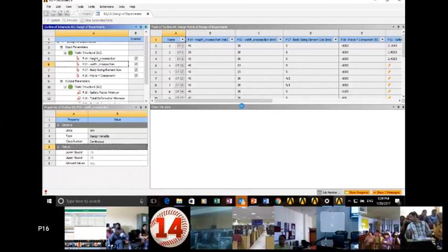Once you are done with the actual optimization of the structure, you will go for Six Sigma analysis. That will be the final step, and the same design you can take to manufacturing. So the response surface plays a very important role in your simulation.